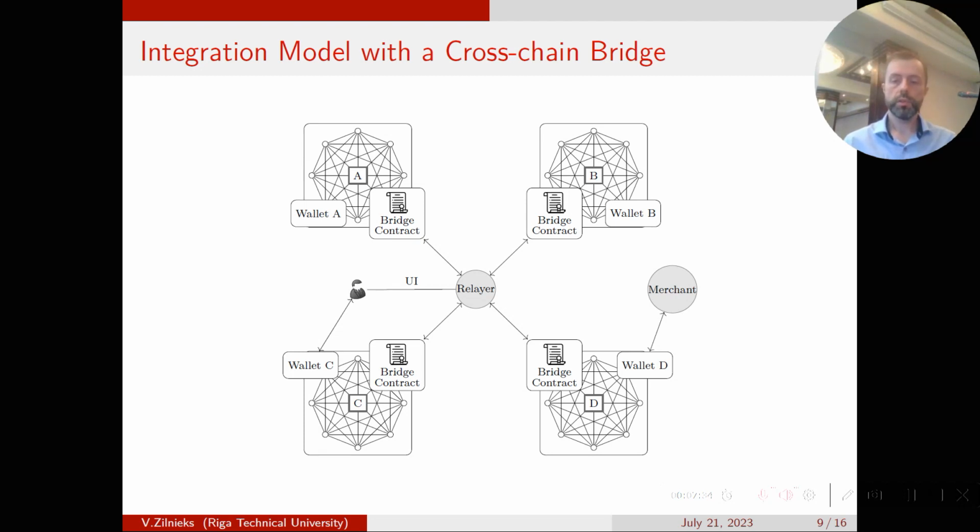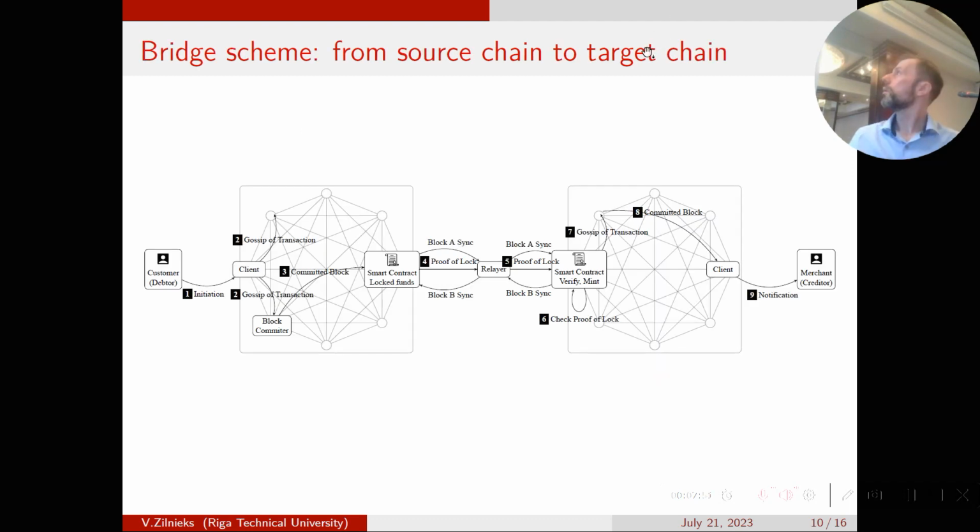So we suggest a simple but meaningful description of the dynamic thermal behavior of a residential home in Salerno. The model is based on a numerical FEM solution, but we have a coupling: the building wall is regarded like a distributed body with the indoor ambient regarded as a lumped body.